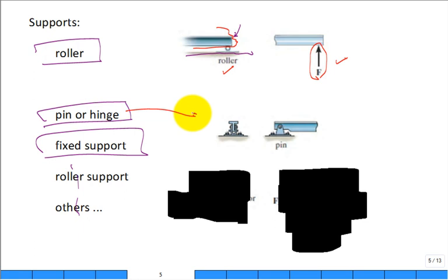Here are two views of a pin hinge. The pinned hinge is right here, looking at it that way, that's the pin going in. You're looking down the axis of the beam. This is the beam that way. I'm going to cut through the pin and replace it such that I just have my beam, and right there at the pin I'm going to have some supporting reactions due to the pin connected to the rest of the surroundings. And it's not that hard.